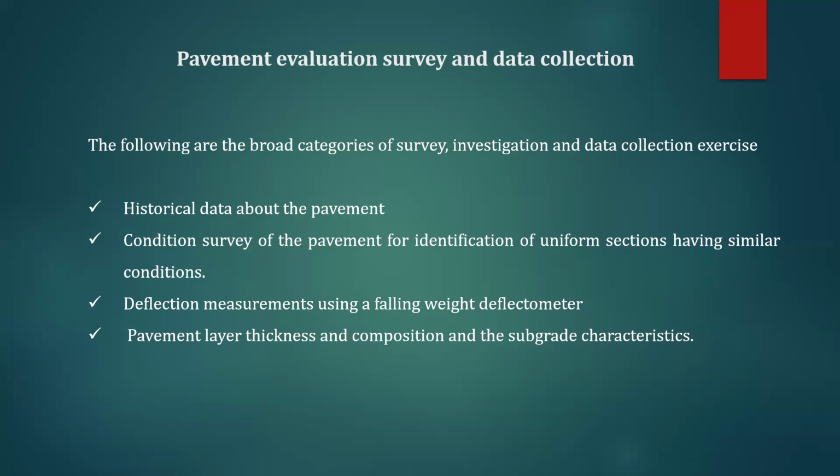So cracking, if the crack width exceeds something like 3 mm, we will discuss in detail in a further presentation. It is most important to understand surface failure. For surface failures, there is no need of going for a falling weight deflectometer analysis. Only if structural failures are there, then how to improve the performance of the existing bituminous concrete pavement? In that case, we should go for this falling weight deflectometer analysis.